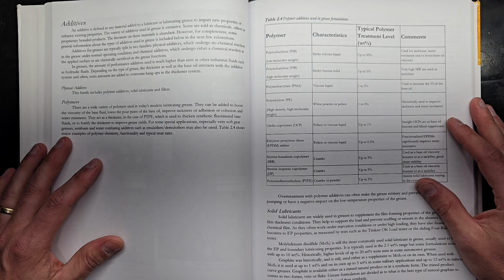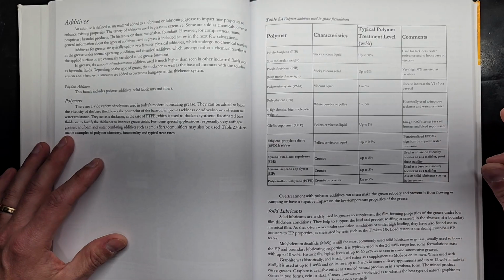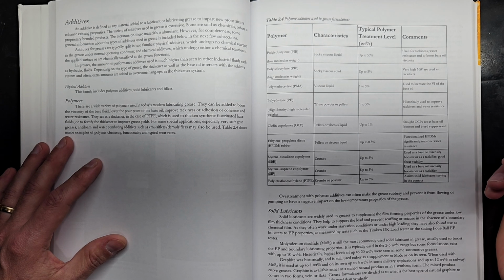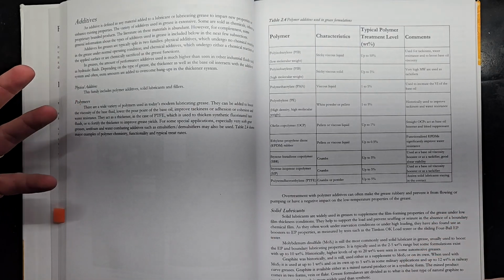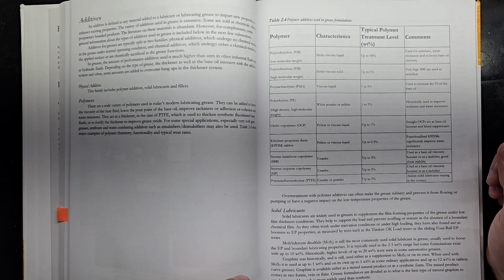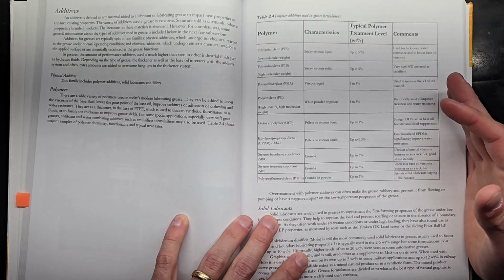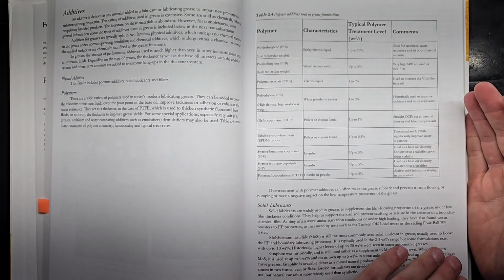Most of the time, as a consumer, you would see that in the tackiness and the stringiness of the grease, because that really helps with water washout and water spray off in our industrial equipment. So they add polymers in to help keep the grease attached to the pivot pins and keep it in place, so that way the dirt doesn't try to wiggle its way in, the grease doesn't wash off, and it stays in place a little better.